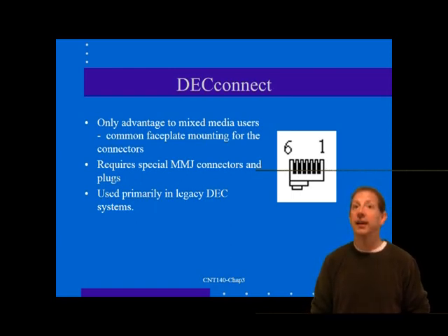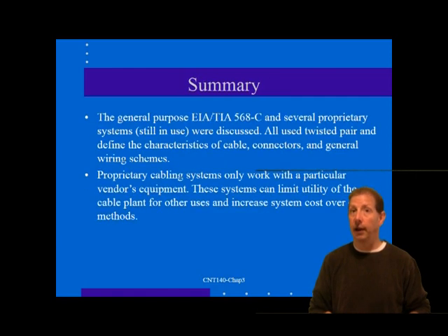The DEC Connect system specifies a clever symmetrical wiring pattern for the data connector that avoids the failure that would result from reversing the order of pin wiring, which is a common error. Ironically, the most frequent source of this type of error would come from the use of standard telephone cables that flip pins from end to end. These are the very cables that will not plug in to MMJ outlets.